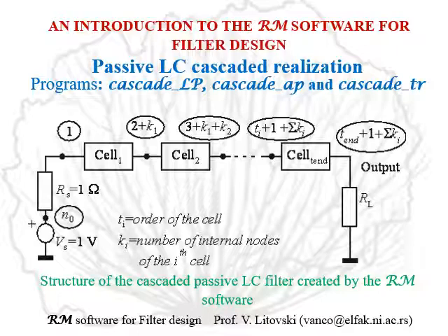And the cells are loading each other, which means that during the synthesis process, one has to take care of the resulting impedance of the rest of the cells, which will load the previous one which was synthesized, and that is both numerically and from the programming point of view a very difficult problem.